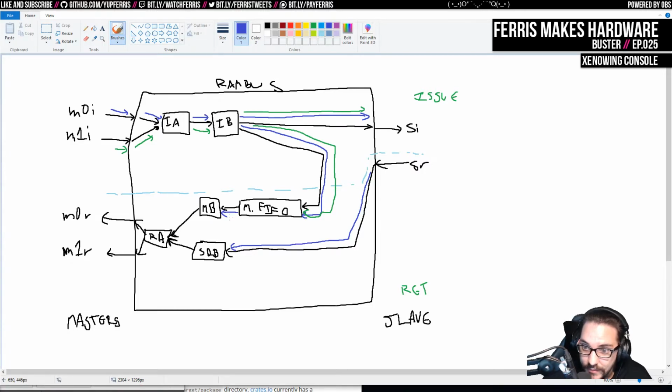Now that's actually fine, because this has just been waiting, since the FIFO stores the data for this other green read too. And also there's some blocking here. So if this FIFO gets full, we won't actually issue reads, so that won't be an issue either. On the following cycle, again, this will all get merged, and then it goes out the proper one. Additionally, in the following cycle, the green one goes back into here.